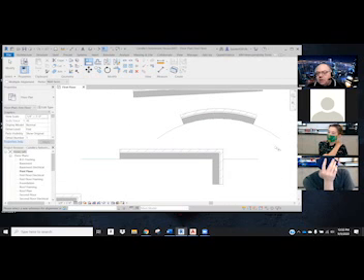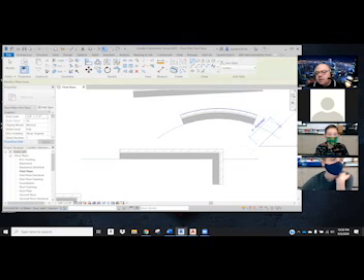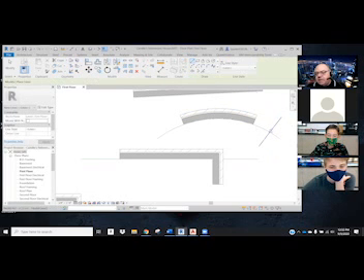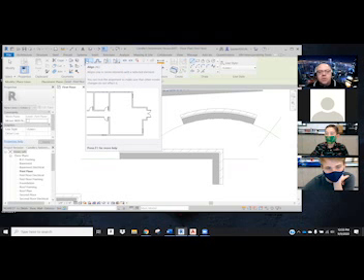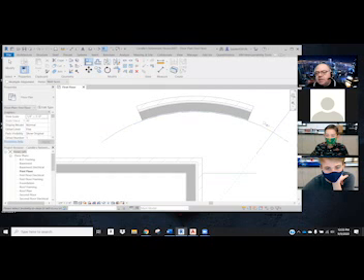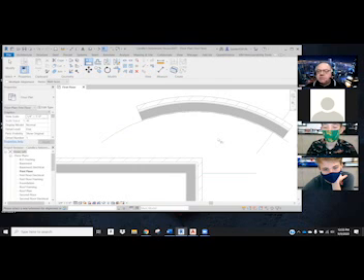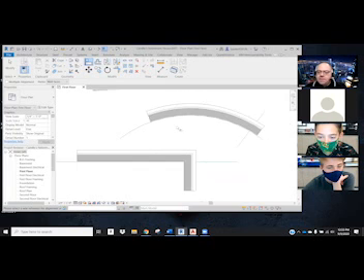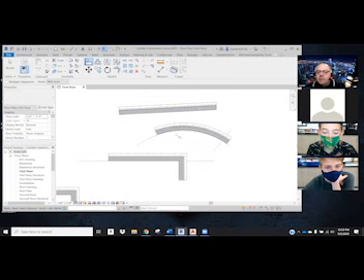Now that's not long enough, right? So if you go in with another model line and give it a destination, and this works for almost all your walls for everybody, you can do another align and tell the wall to lengthen to that point. And you can kind of work and build your wall that way. So hopefully that'll help you build your rounded tower to the radius that you want without spending a lot of time figuring out the math. We don't want to spend time doing math if the software will do it for us. Hopefully that helps for you. You can come back and watch this little video part, zoom to it, and you'll be fine.